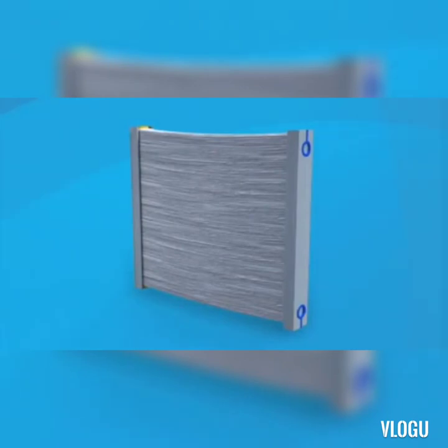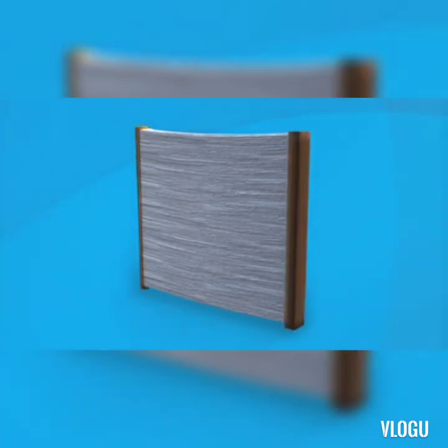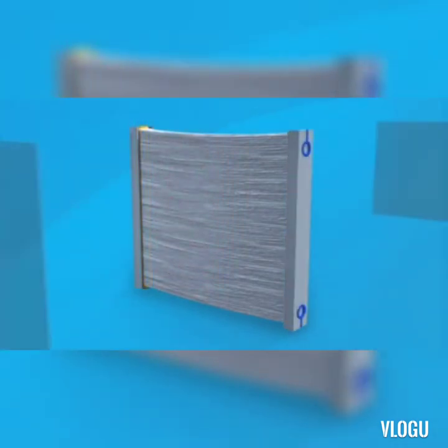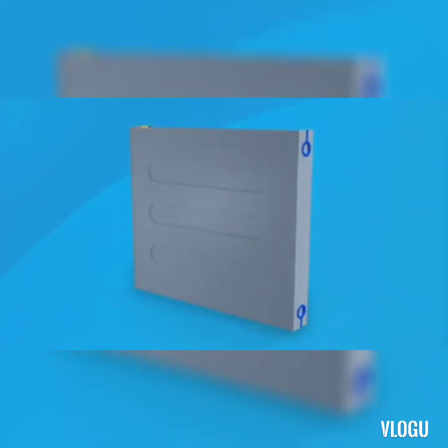The membranes are arranged horizontally into modules. Each module contains 30,000 membrane fibers held by resin at each end. The membrane fibers connect to a single common module header. This is where the filtrate is collected. Two plastic shrouds encase the sides of the module. The shrouds protect the fibers and draw the feed water upward through the modules.